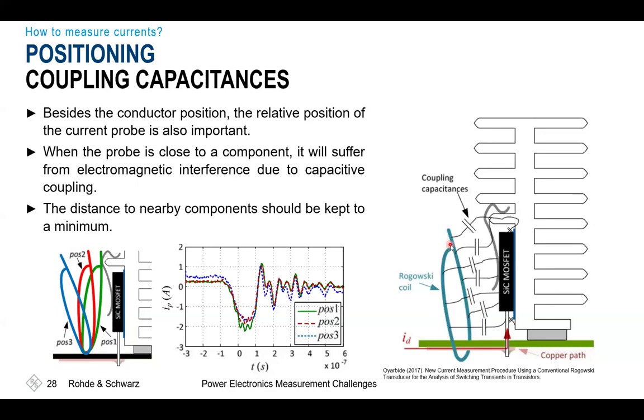Yes, we have a weak coupling between the DUT and the measurement system itself, but we have a long wire in between, which takes a lot of turns inside the Rogowski coil. Also inside, there's a feedback loop to ensure that the loop is closed. And thus, these systems are highly resonant and also highly dependent on their resonant environment through cross-coupling effects. As you can see here, you'll see different readings in terms of the current. You'll see different overshoots, ringing, and modulations on that. So it strongly depends on the position.